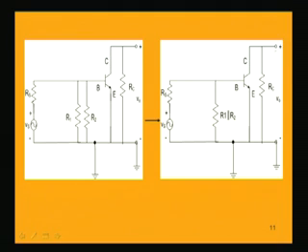Now, after drawing this AC equivalent circuit, we can go on to find the required parameters like voltage gain, current gain, etc. for this particular amplifier. But one obstacle exists here because of the presence of this physical transistor. As shown here by this physical semiconductor device, which is a transistor, here of course common emitter, if it is kept like this, it will not be possible to analyze the circuit in terms of actual electrical engineering. That is why we have to replace this transistor also by its equivalent model.